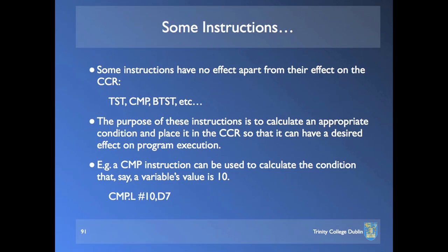can get very far. So if the assumption is that the condition code register is being affected by an instruction, you have to slow the pipeline down to allow the effects to be posted to the condition code register before you can even partially execute the next instruction. If you remove that assumption and say that no instruction affects the condition code register unless you explicitly look for it, then the succeeding instructions which are being partially executed don't need to wait for the condition codes to be posted. So that's a big reason for not having condition code registers affected by every instruction in a RISC machine.